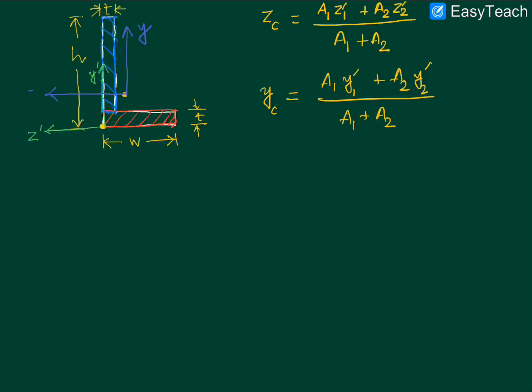This we denote as y and z. And whatever we do after this has to be in reference to this y and z axis. Now please note that the zc and the yc values that we had found out are with reference to this starting origin, which was only a matter of convenience to understand the geometry.